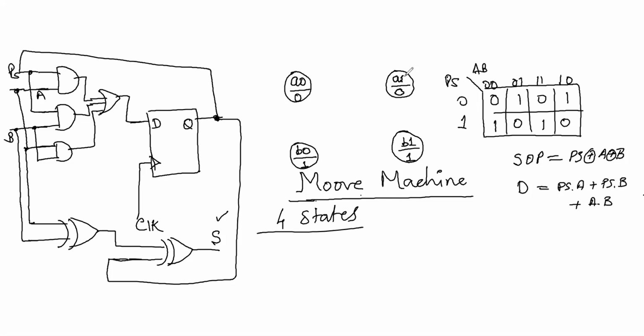So now draw the transitions. Now this is when your partial carry is 0. That means you are starting off, your input is 0. And if you get 0, 0 as 2 inputs, your sum will be 0, your partial carry will be 0. So you remain in the same state for 0, 0.